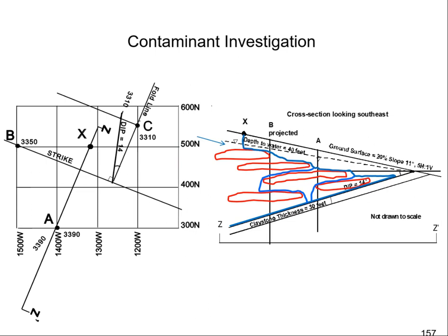What happens is that any of these clay lenses, if we knew how big they were, thick, laterally extensive, impermeable, shallow, all those things we don't know, if it was relatively shallow and it was contained, for example, within this upper clay lens, you could put a slurry wall down to that clay lens and contain it and treat it there.